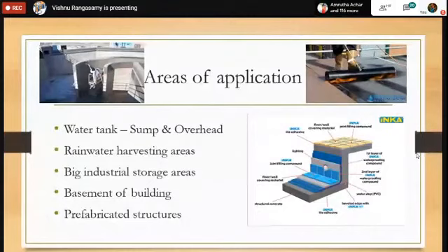So we did a renovation work. It was around 6 floors, an apartment building. On the 3rd floor and 4th floor, it was completely damp, in the ceiling it was completely damp. So we didn't know where the water was leaking from. At last we found that it was the drain pipes that were left in the sunken areas that were connected to the main slab.